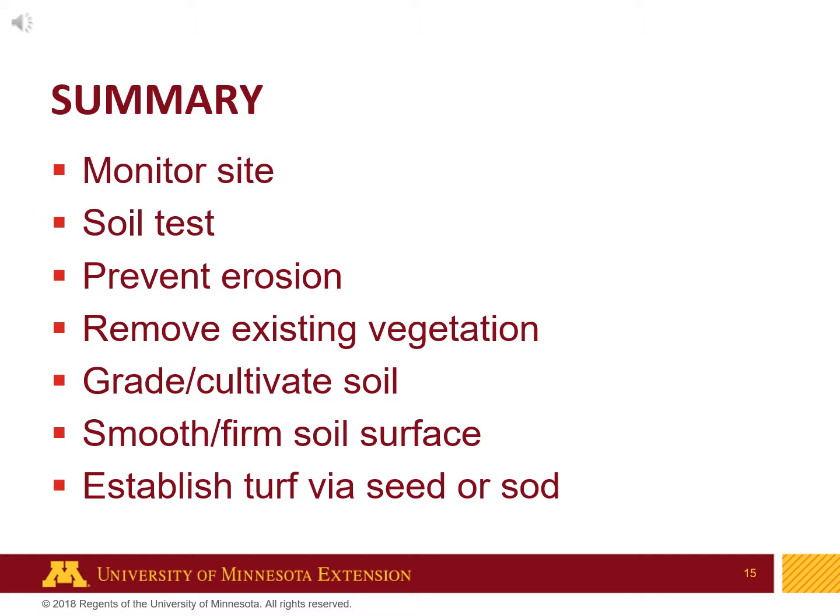As a brief review, the soil preparation process includes monitoring the site in person, conducting a soil test, installing erosion control measures, removing existing vegetation, grading or cultivating the soil, smoothing and firming the soil surface, and is completed by establishing the turf with seed or sod.